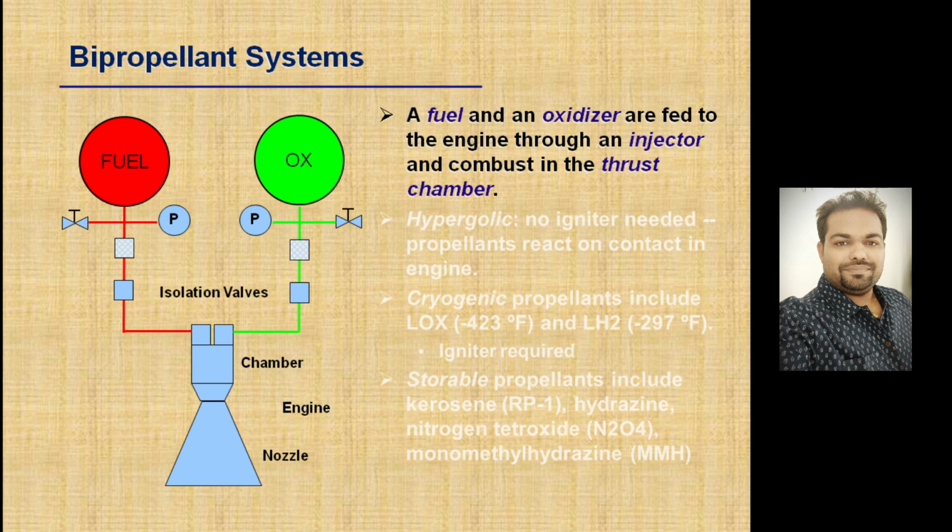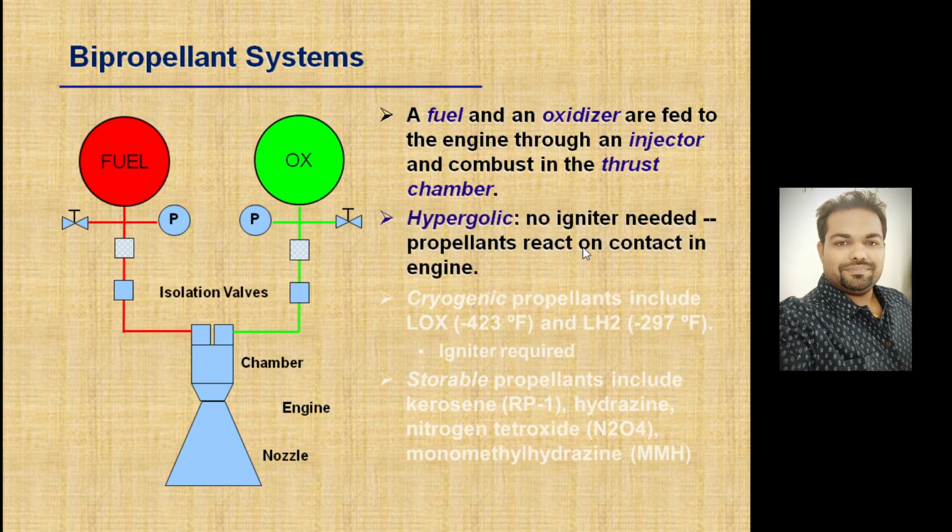Some of the bipropellants may have hypergolic propellant. The moment they come into contact, they will react and combustion occurs. So that means no separate igniter is needed in the case of hypergolic propellant. So hypergolic, no igniter needed, propellants react on contact in engine, right?